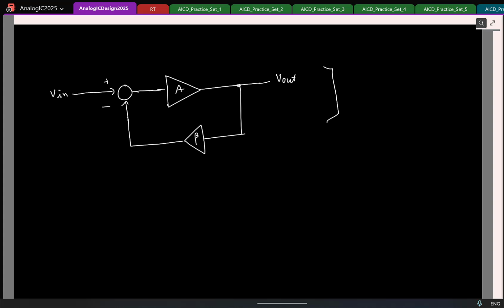Voltage control? Why? Yeah, at the output, the negative feedback is trying to make the output voltage to be a constant. So at the output, it is a voltage or a current source. At the output, it should be clear, it is a voltage source, and this output voltage is controlled based on another voltage at the input.